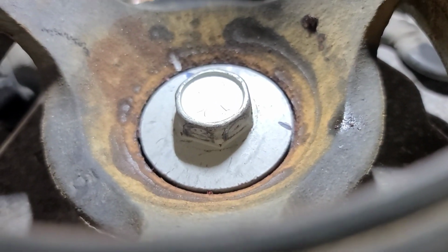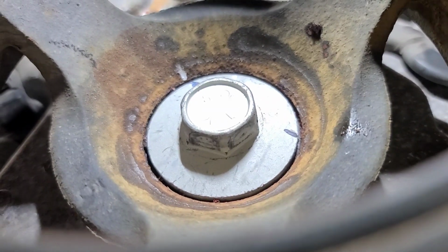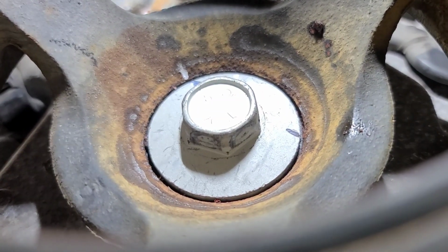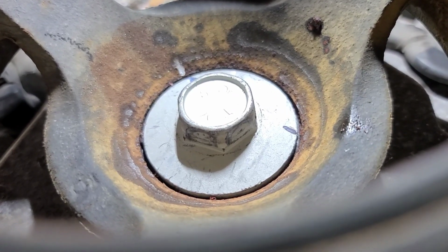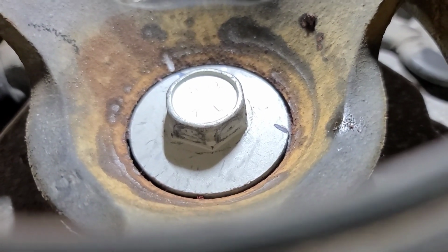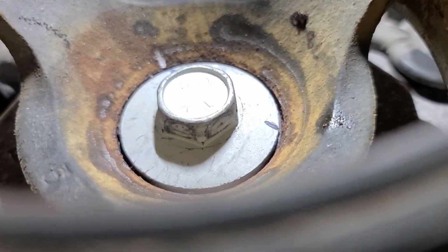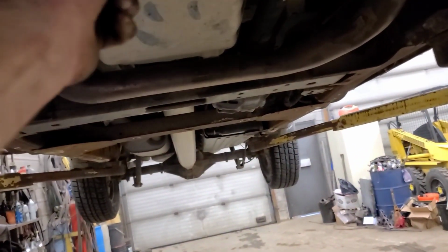So there it is tightened. Like I said, you need a 4-foot bar, big heavy torque wrench, or a big heavy power bar. I use a big Snap-on 1/2-inch drive one, and it's got to be by feel 250-300 foot-pounds to tighten that. And then take your wrench out. Don't forget to take the wrench out. That'll cause a problem if you don't.